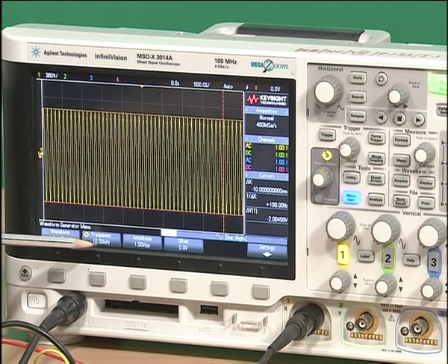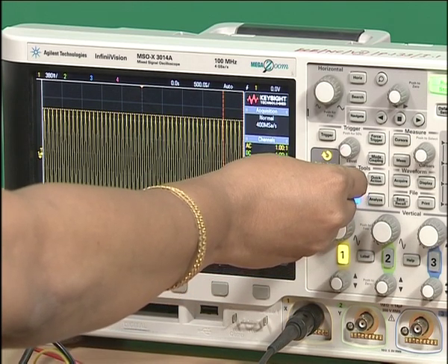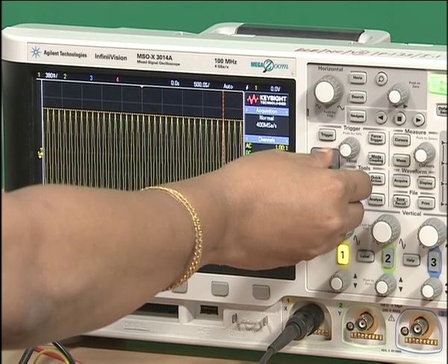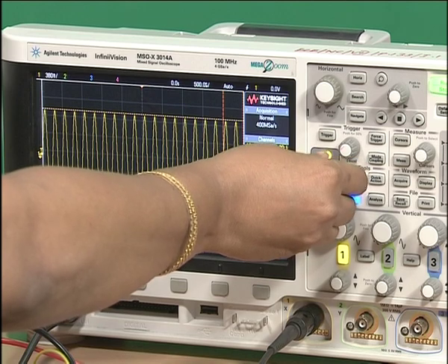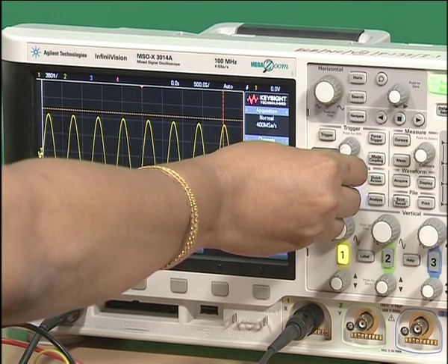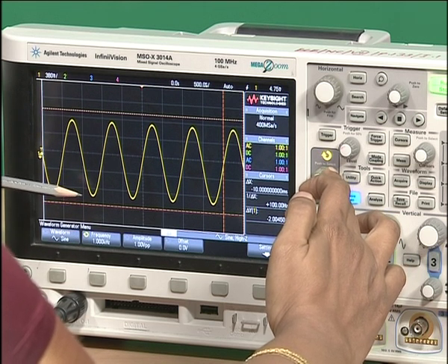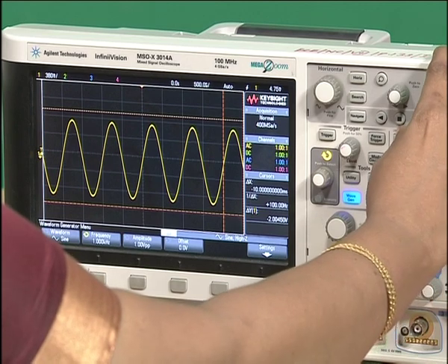Now, as the frequency is varied and when it is brought closer to 1 kilohertz, you can see this amplitude getting attenuated. So, we will see as the frequency is varied. Now the frequency is reduced. The peak to peak voltage remains constant, which is the same as 2 volts, so that is within the pass band, and as the frequency is reduced and brought closer to the cutoff. So, now it is at 1 kilohertz, we will verify the peak to peak amplitude. This peak to peak amplitude must be 1 by root 2 of the maximum voltage. In decibels it is 3 dB and it is termed to be the cutoff frequency.